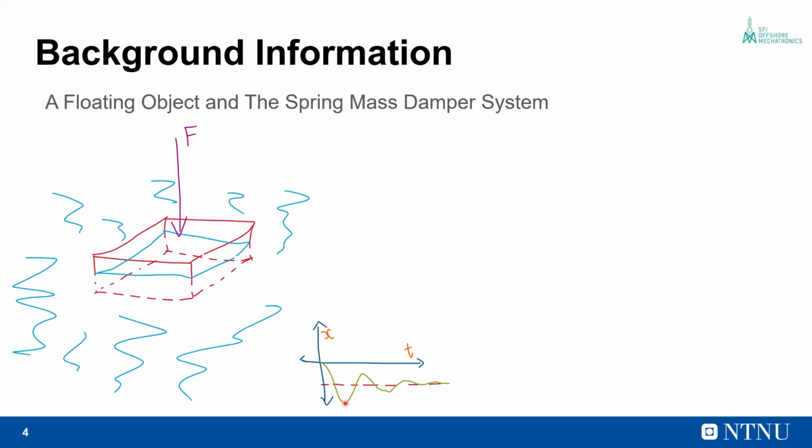At this point, buoyancy exceeds the total downward forces and the barge will start moving up. Again, it will overshoot the equilibrium position by a slightly lower amount. It will come down again, and this process continues until the motion decays and the barge finally comes to rest at the new equilibrium position. Now, if we analyze the response, we see that the amplitude of oscillation is reducing, and this points to the fact that energy is being carried away from the system.